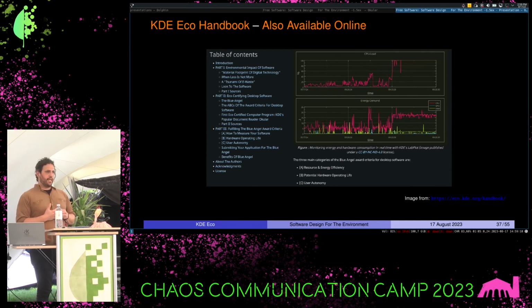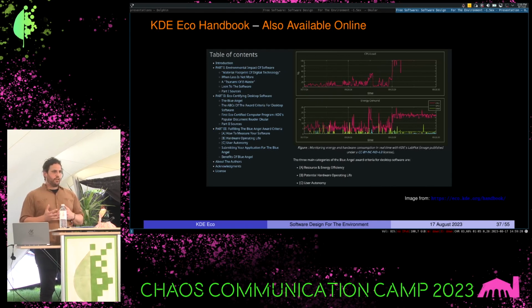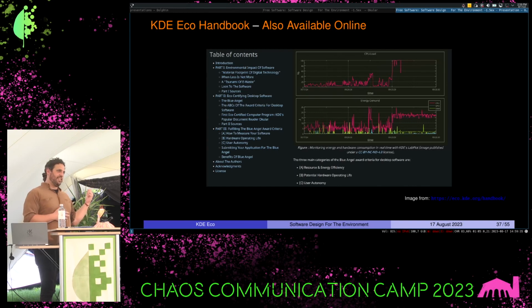Better ones can get like 1,000 measurements per second. However, you're going to be out 300 to 400 euros to buy one. If you're interested in just checking this out, but don't have 500 euros, you can invest 10 euros and buy a power plug, hack it, and turn it into a power meter that gets about 1 measurement for every 200 milliseconds. And that's also documented in this.